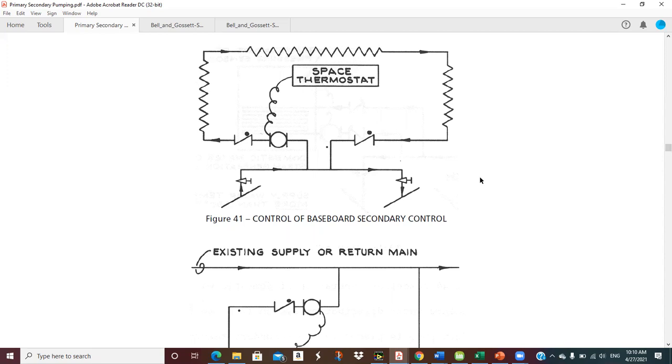Lots of air blowing through the doors because they're opening and shutting a lot. And so you can put in a situation like this where you put all those baseboard heaters in, and you could have one, you could have several circuits, whatever. And when you get below set point, the pump runs and you pump some good warm water through those coils, and by natural convection, that heat rises into the space. So that would distribute it pretty nicely.